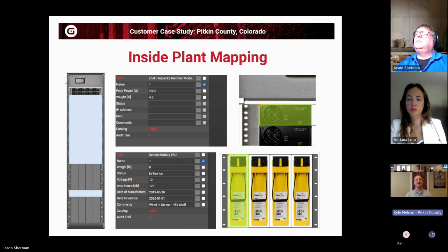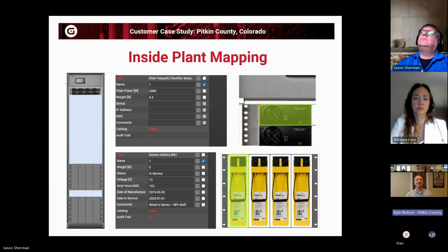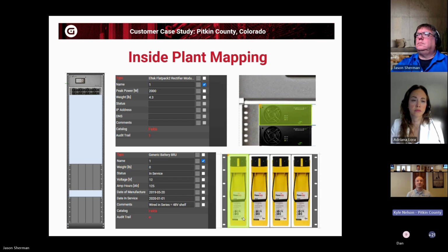This is, for example, one of our racks for our battery backup power at our sites, right? Zero fail mission critical communications equipment. We've got to keep those microwaves alive if the generator runs out of fuel or fails to start, or until it starts, I should say. So at the top of that rack, we have one of our rectifiers, and in this particular rectifier, there are 8 open slots when it comes from the factory that we can load these rectifier modules into, that then take the incoming 120 volt power and rectify that into 48 volts to maintain those batteries.